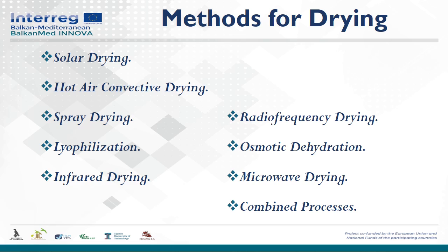Infrared drying. The solid food is exposed to a source of infrared heating in this method. Here, most of the solids have a low thermal conductivity, and the rate of heat conduction to the interior is very slow. The application of infrared radiation is primarily intended for surface treatments of the food.